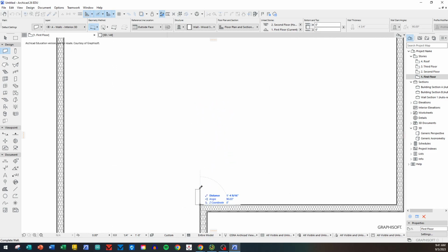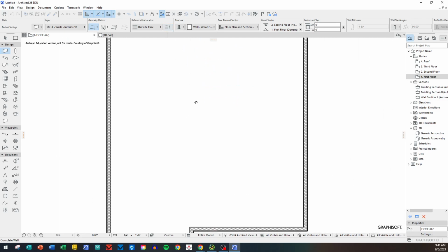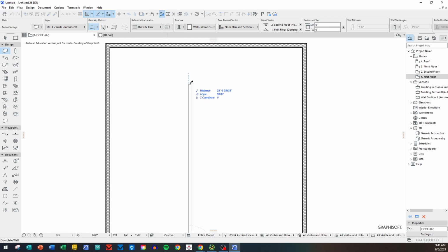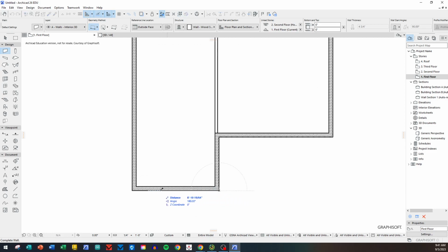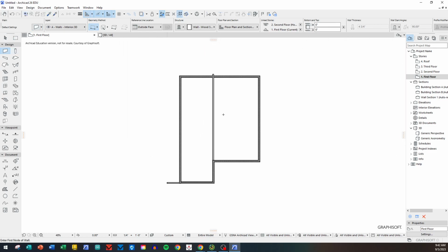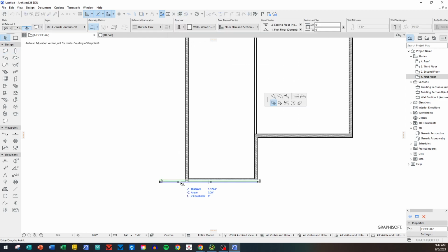Notice how that hits. That's not going to be the way I want it. I want to flip that wall over. There we go. Flipped it over so the drag side's still the outside, but my outside is to my left instead of my right. I'm just going to drag it straight up through the back wall. There we are. Now, I can go like this at this point and drag a line straight out here to my left again. So I've now created a wall that is a bearing wall, and I can change that to be a 5.5-inch wall if I want. This house isn't big enough to need that, so we're not going to worry about it. For my classes, I typically teach it to put a 5.5-inch wall, but I don't deduct if it's not.